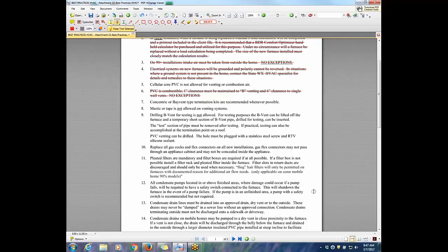If you go out to the middle of a B-vent pipe, there's a big air gap between the inner and outer liner. If you drill the hole there, because that outer liner is such thin material, when you pop through it, it has a tendency to pull your drill bit in really fast. When that happens, it'll actually crush that inner liner or compress it down.